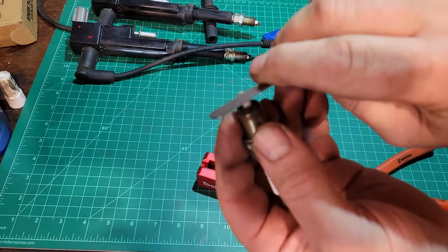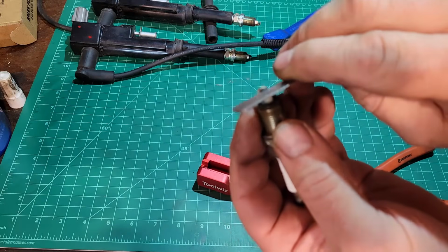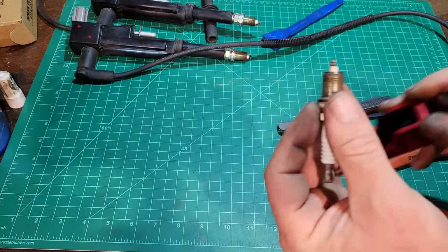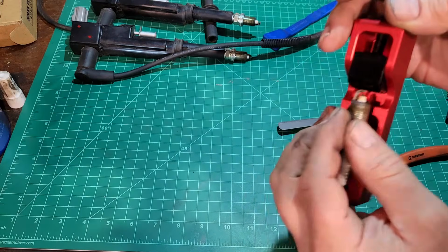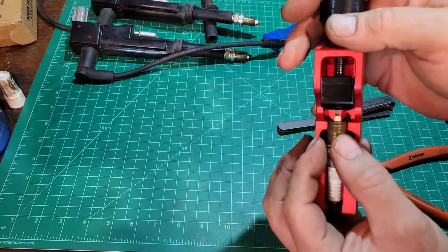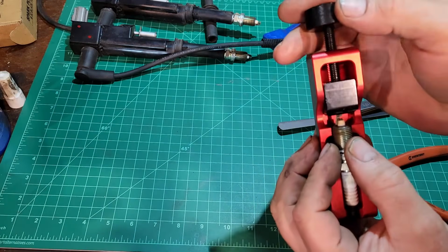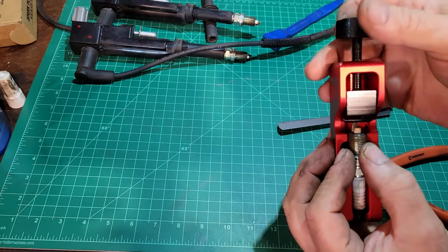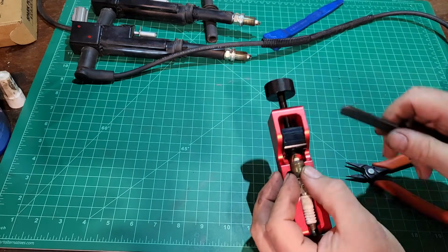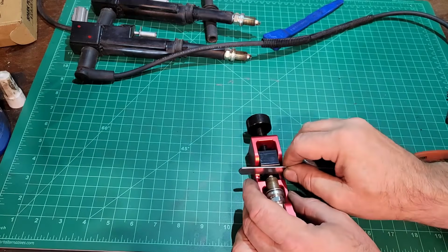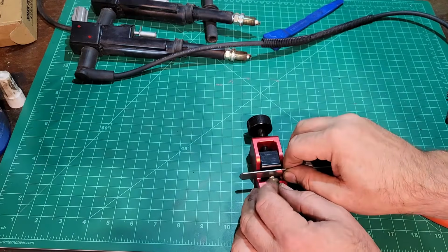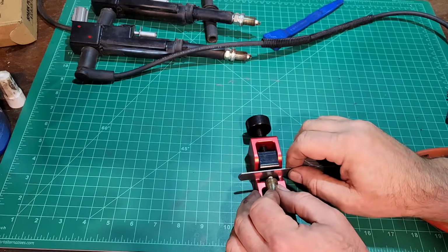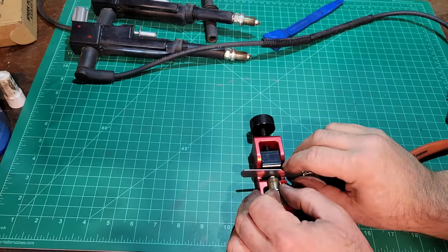Make sure your spec fits. That's a pretty tight fit right there, just opening it up. But I never like ending on increasing the gap. I always like to push back down on that ground strap just as a final adjustment. And these tools are really cheap. This was an Amazon one. And you put the feeler gauge in, and I put it lengthwise so it goes with the ground strap.